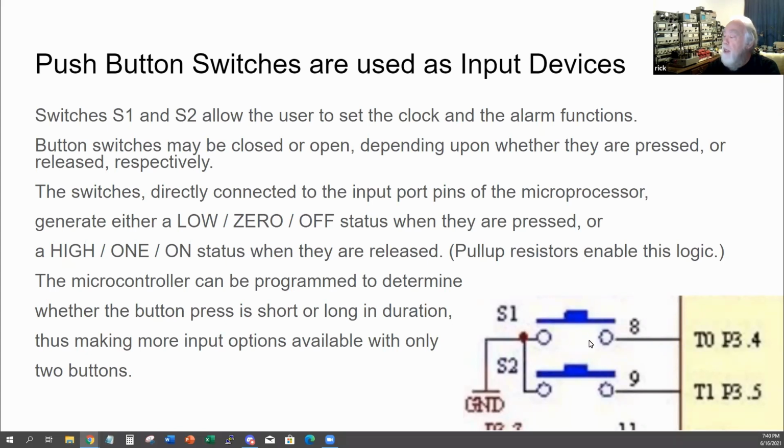So just by connecting a button to the power supply return lead, we can cause the computer to perform different functions. And one button can perform more than one function because you can do a short press and the computer can time how long it's pressed. And if it's less than a second, it can perform one function. But if you hold it down for a second or two, the computer can determine it's a different function and can act differently on that push.